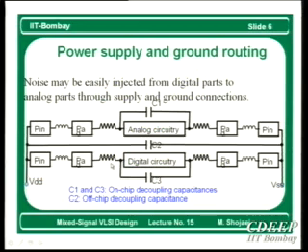Okay? Of course, coming to C2, if you have done board design, you know we always connect a big capacitor from VDD to VSS on the board. This is the reason we want, even from outside, from the board level also, to short circuit VDD to VSS at high frequencies. Means that there is no noise or difference between noises which are present on VSS and VDD. At least we can keep them at the same level. Means that we want to keep the DC difference constant.